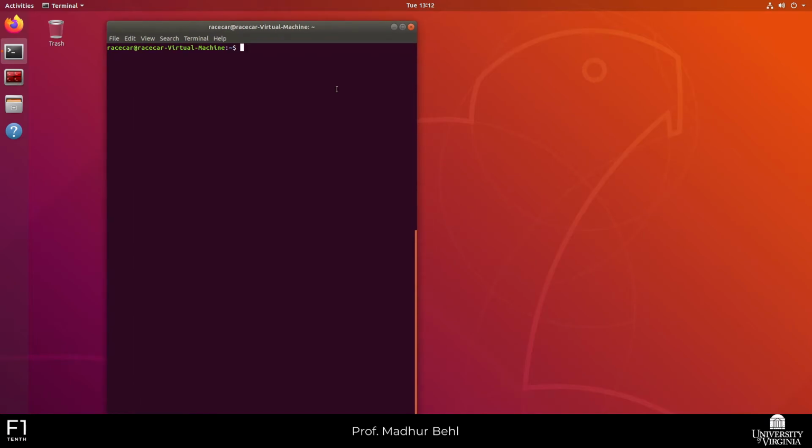And so once you are able to connect and see all the topics, you can always bring up the visualization. So you can do that by saying roslaunch. The name of the package is f1tenth sim visualization. We have a file called racecar.visualization, but you need to provide some arguments. So the first is computing ID with a colon equal, and this is my computing ID.